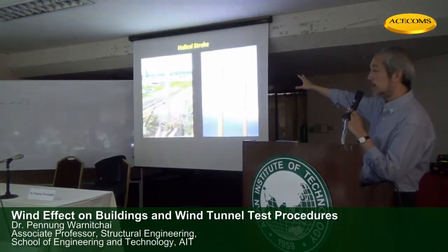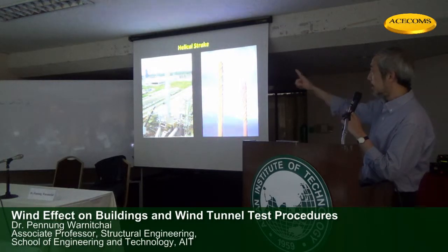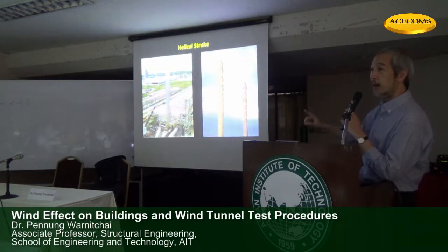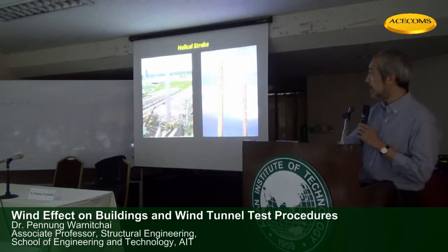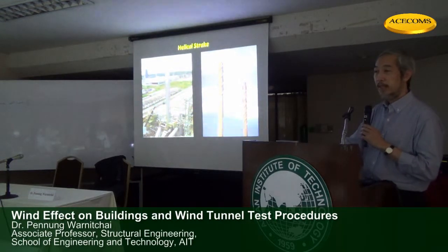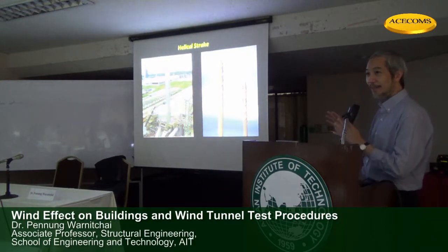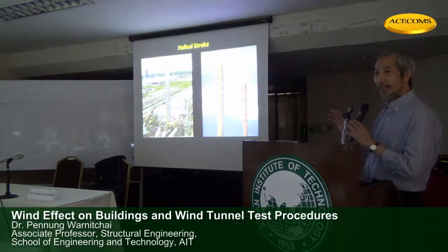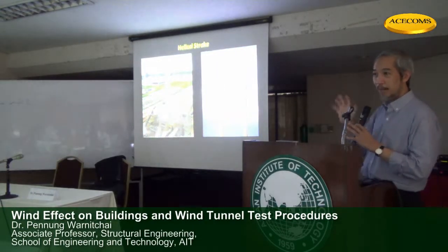Yeah, this is a practical solution used in design by practical engineers: wrapping helical wire around the stack. The idea of this is to shape the vortex at different phases, so that it will not correlate. It's like you help push a car, but not at the same time. You ask one to push at a different time, so it will not combine into a big force.